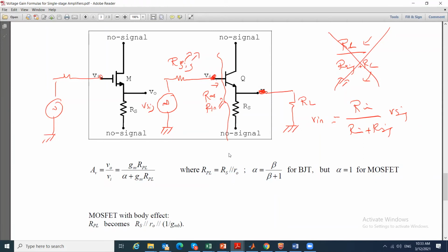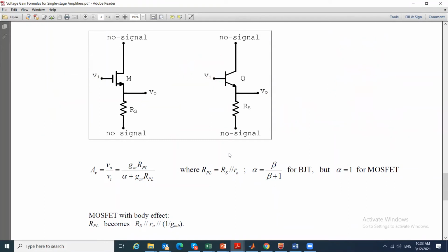Now, I'm giving you the motivation, but what really matters is that at this stage I know that if I have this circuit, looking into it, it will have a large Rin, and the gain for this circuit will be based on the effective RS. Of course, if I have an external R load here, this will be RS prime, which is RS parallel to R load, and so on. But the gain, independent of what the load or RS parallel to R load is, is approximately 1. Clear?